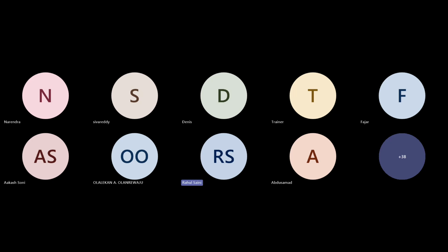Okay. The reason why I was asking is that the gas mixture generated from the electrolyzer comes along with water, and there is oxygen itself. Oxygen and hydrogen have different molecular weights and specific gravities, but they are in gas form only, right? Yeah, those are in gas form, but they have a specific gravity difference as well. How will you separate gas and gas, like methane and air? There is no separator which separates methane and air.